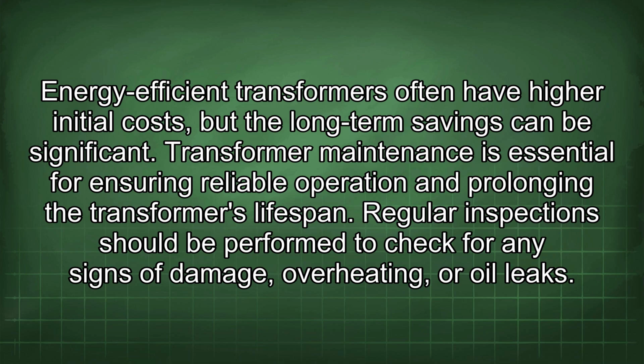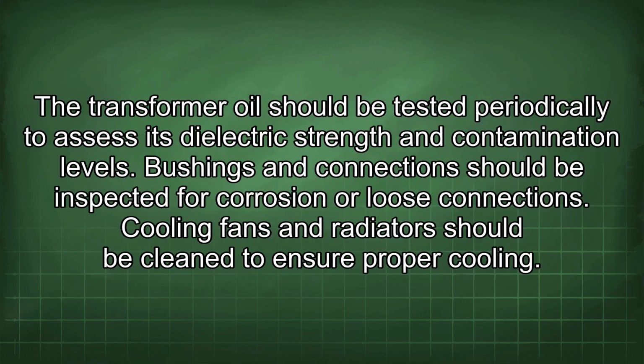Transformer maintenance is essential for ensuring reliable operation and prolonging the transformer's lifespan. Regular inspection should be performed to check for any signs of damage, overheating, or oil leaks. The transformer oil should be tested periodically to assess its dielectric strength and contamination levels. Bushings and connections should be inspected for corrosion or loose connections. Cooling fans and radiators should be cleaned to ensure proper cooling.